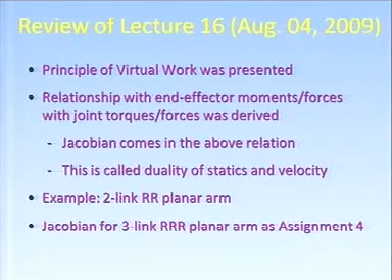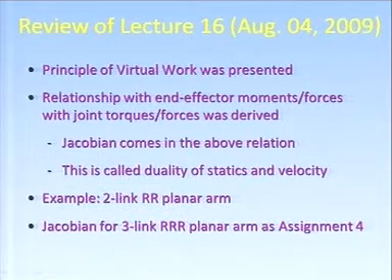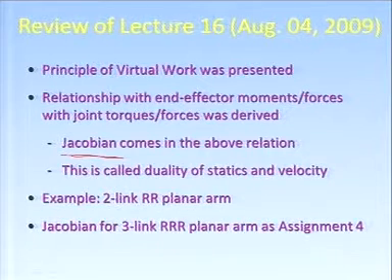So let's start with the review of our lecture 16. I have discussed the principle of virtual work in statics. Then the relationship of the end effector moments and forces with the joint torques and forces was derived, and there we saw how the Jacobian comes into the above relation. I have mentioned that this Jacobian appears in statics as well as dynamics as well as kinematics.